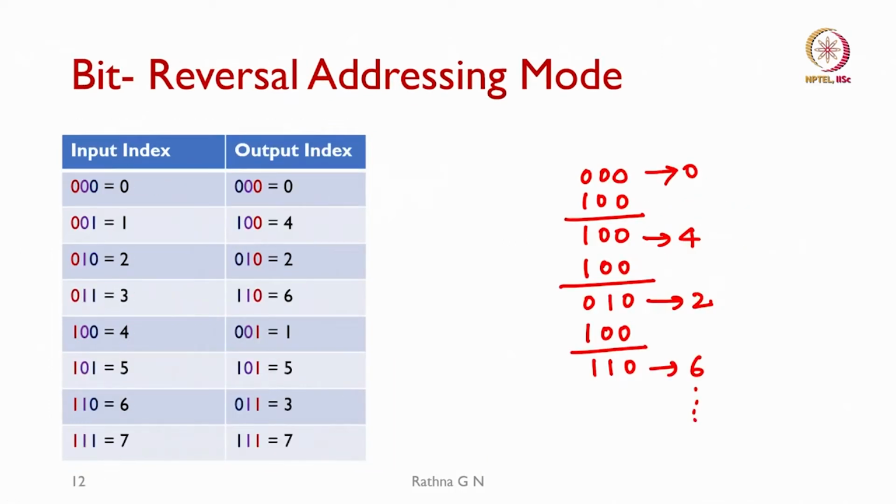So, coming to the next, why do we need bit reversal addressing? Just now I said how it is going to be represented. We know this is the input index I have, but I want the output in this order. If we do it in software, it will take multiple clock cycles. Instead of that, can we do this bit reversal in the hardware?